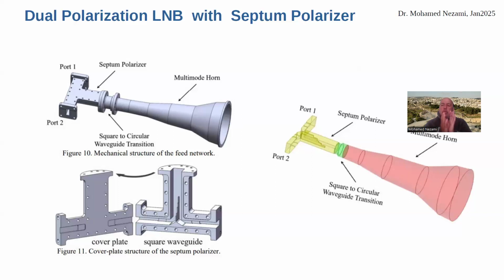Each of those could either have the same information modulated, which you could use in comparing fading and fade out, or totally independent modulations, like you would see in DirecTV, Ku band and Ka band TV programming, where two channels would be on the same frequency, yet multiplexed. You can decompose them because of the orthogonality between them, where one was sent on the vertical and the other on horizontal, or vice versa.